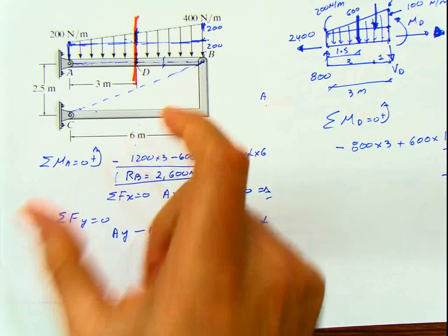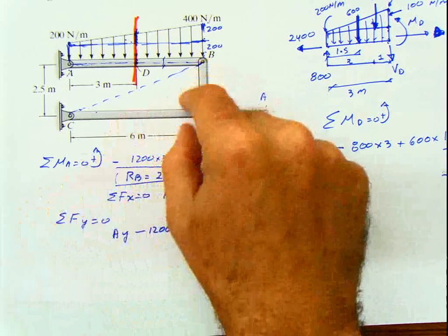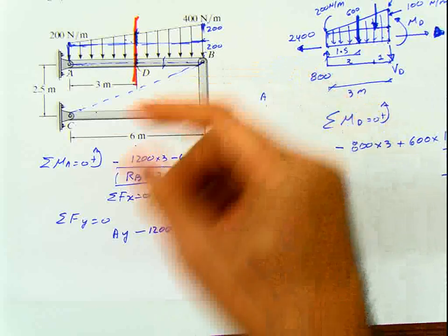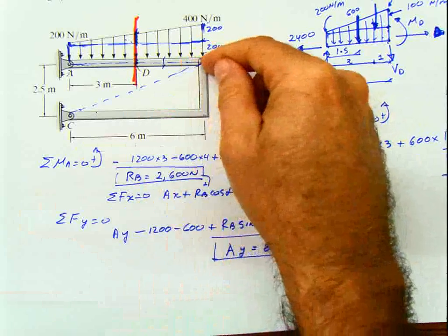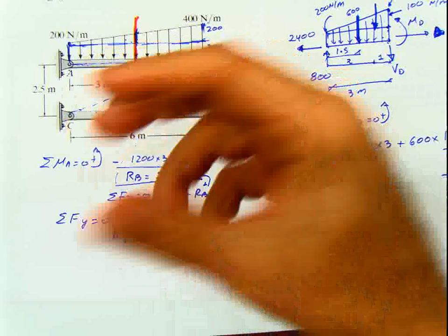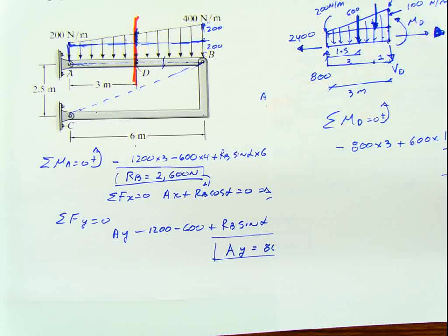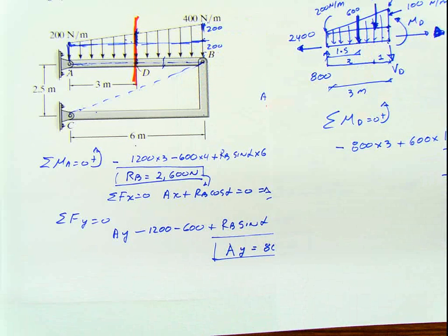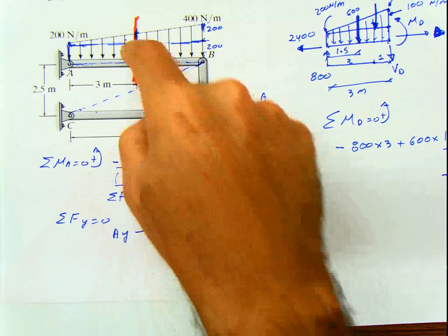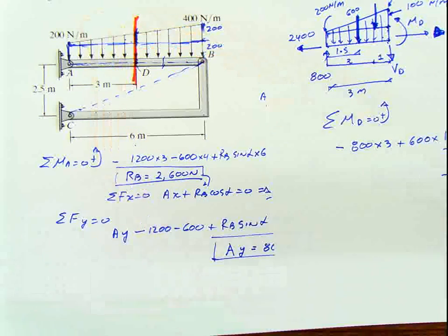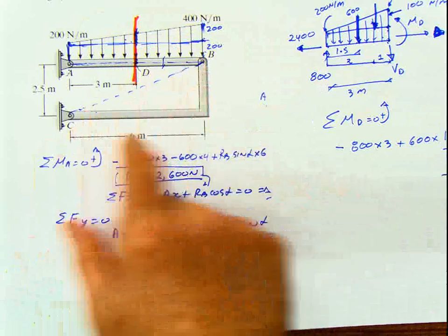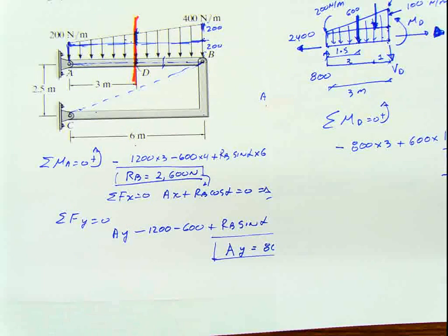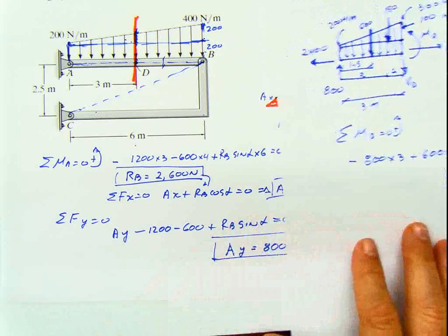Even if it wasn't a two force member and you have a structure like that and you have a force here, then what you have to do is make a section, treat it like a truss, make a section and separate both sides and try to get forces from one and transfer the forces to the other one, or do the analysis of the joint, or do something. But you can't apply the concept of trusses because you have intermediate forces on the elements. You have to treat this like a mechanism, which is a different situation, but it's similar somehow.